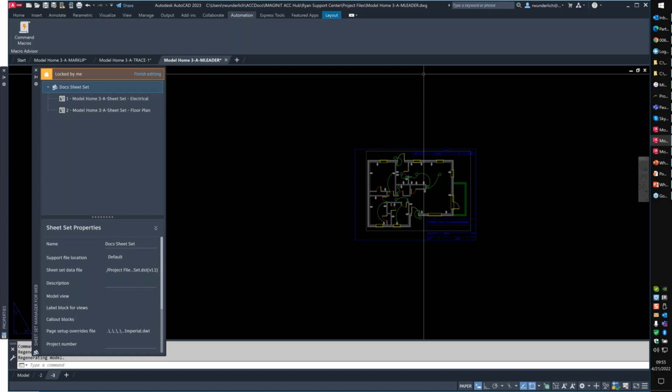But I do know what you're referring to. Usually when I'm doing continuous dimensioning, I actually will end up turning off extension line 2 or extension line 1. I will turn one of them off for the dimension style, and that's how I find to get around it.